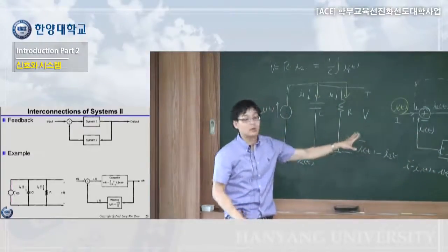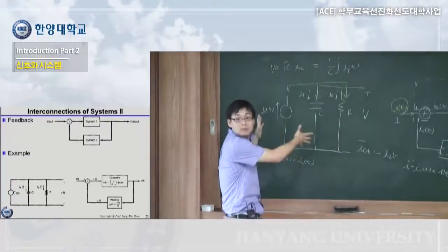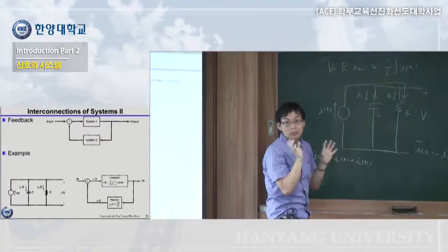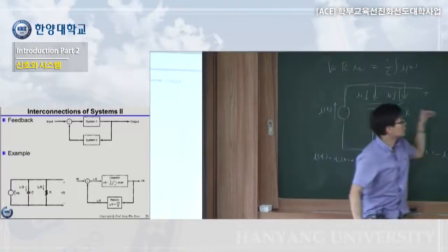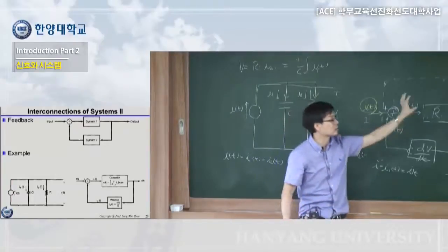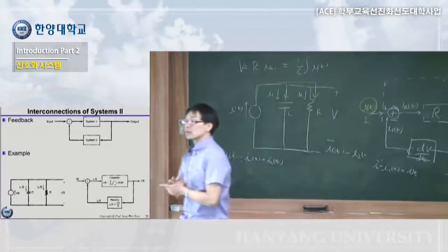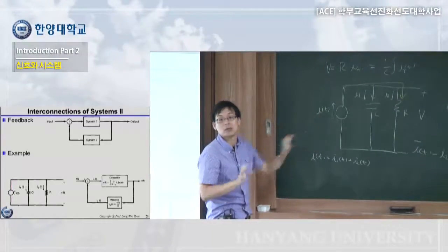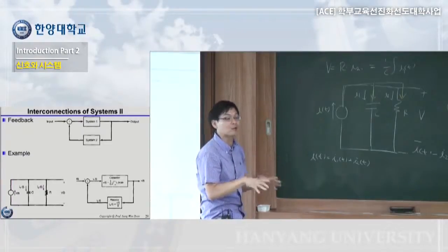So this system and system on our slide are same system, describe the same system, but we can model them differently. We can model them either what we show in the slide. Straight line is capacitor, feedback is resistor, or you can use the other way. Straight line as a resistor, feedback is capacitor. So we can design either way. So even though you model the same system, you can model them differently. So if you find a way to simplify the model, you have a much easier analysis.